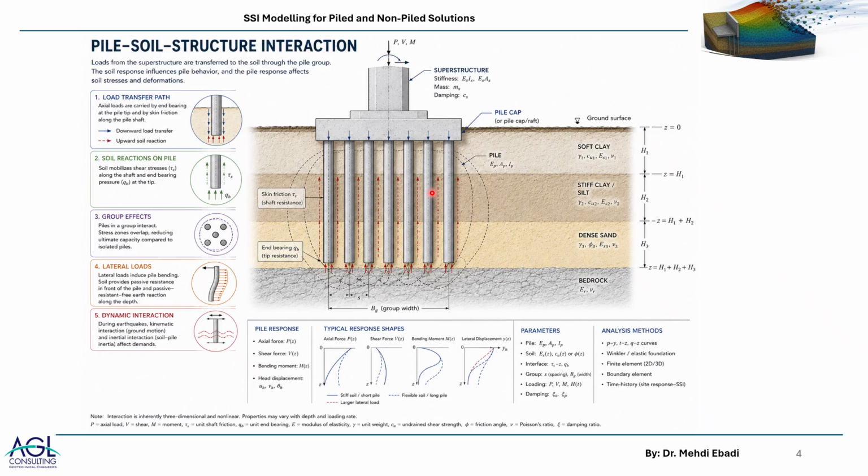And the spacing, diameter of the pile, and behavior of the soil are of much more importance in such cases. So normal parameters that we usually consider, for example, for deformation, like stiffness and these kinds of things, should be captured in much more advanced models, which we'll discuss later.